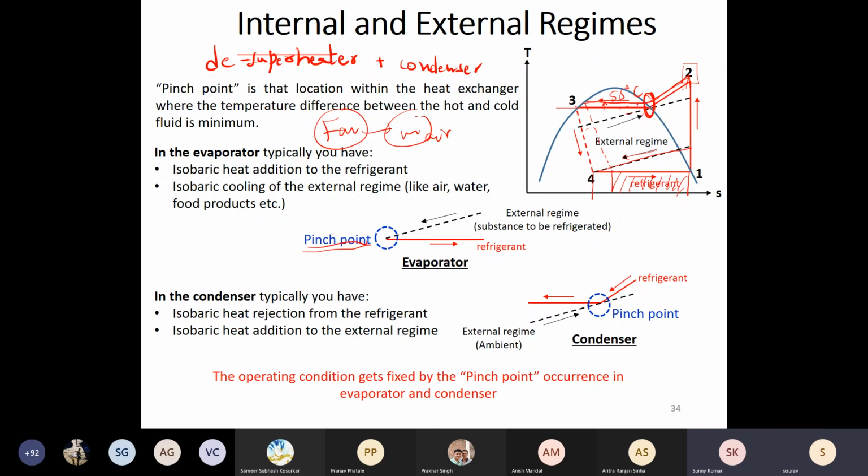I had to push my condensing pressure. So your compressor will also have to compress more. You obtain a smaller refrigeration effect. Okay, and that's why we try to subcool also, so that whatever we are losing now here, we try to gain it back.